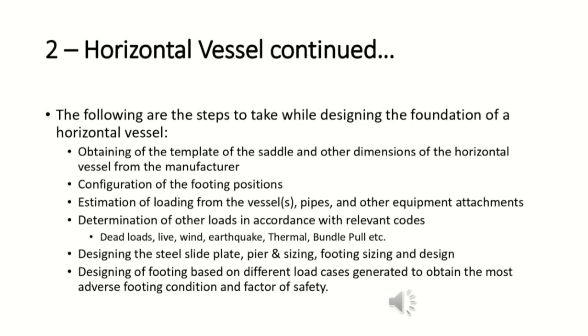4. Determination of other loads in accordance with relevant codes. For example, the dead loads, the test dead load or operating dead load, live load, wind load, earthquake load, thermal load, bundle pull load. 5. Designing the steel slide plates. Designing the pier after doing sizing. Footing sizing and design.